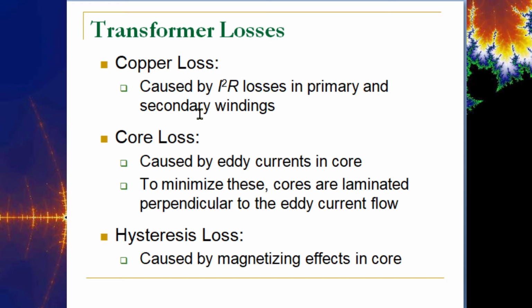A lot of times you get two things that typically happen. You can have an eddy current that can happen when you have these cores, but you can also have what's called the skin effect, where the electrons tend to travel on the outside of the wire no matter what size diameter the wire is. This has caused some manufacturing of wires to be hollow in the middle, since that's typically not used anyway when electrons travel from point A to point B.